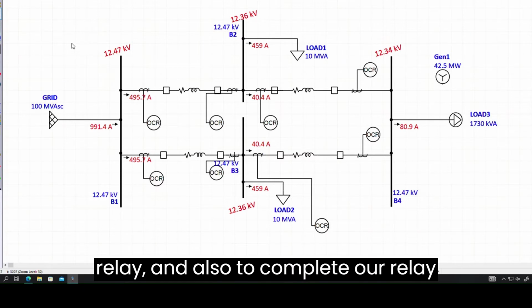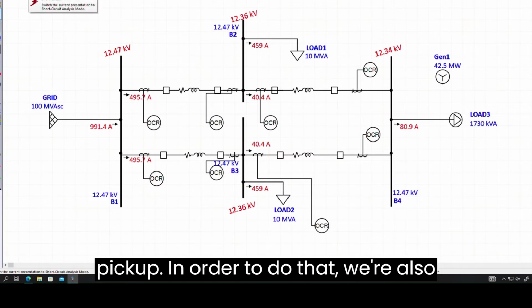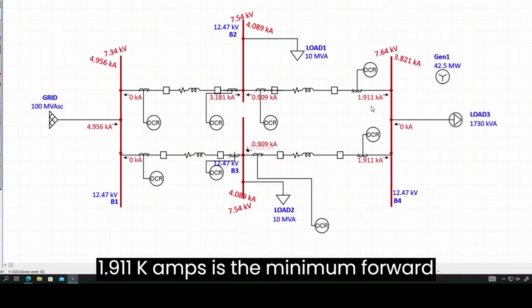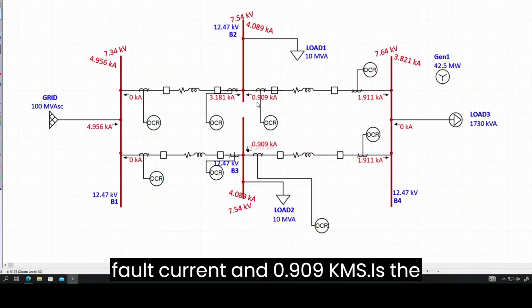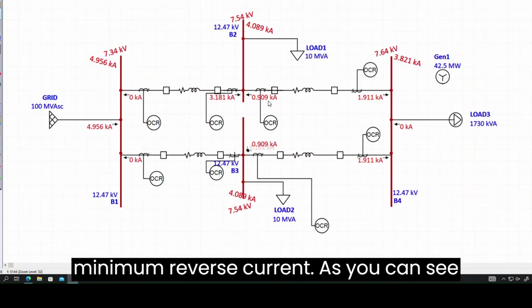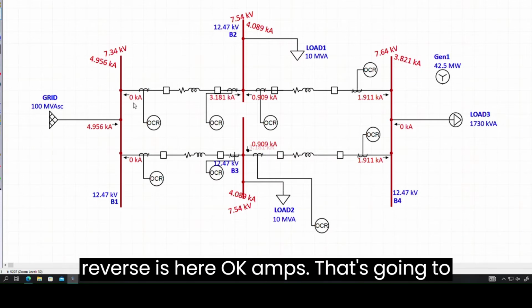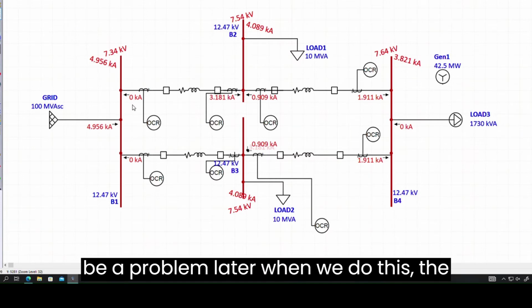And also to complete our relay settings, we're going to need the I pickup. In order to do that, we also need the minimum fault currents in the system. We found that 1.911 kA is the minimum forward fault current and 0.909 kA is the minimum reverse current. As you can see here in bus 1, the reverse is 0 kA. That's going to be a problem later when we do the coordination.